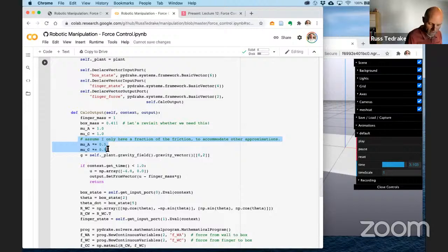And now the magical thing is, as this finger starts moving here and here and here, it will actually pull back down also. So a fairly simple desired trajectory in the virtual force frame, if you will, could also achieve the task. And I'm going to try to talk about that a little bit more geometrically, make sure you understand the conditions for that next time. And that is sort of at the heart of impedance control, of trying to program the virtual interactions between your unknown forces and your robot.